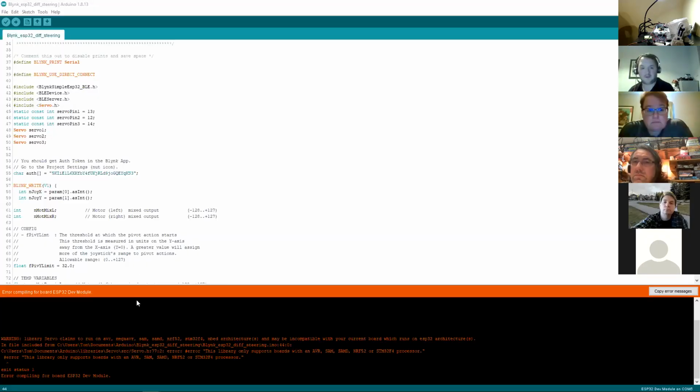Yeah, because how do I? Oh, this is. Have I shared that screen correctly? Yes. Yeah, that's what I'm getting. It's saying the library supports boards with AVR, SAM, SAMD, NRF, etc., but it's not happy with the ESP. Yeah, that's because I'm using, let me have a look to find it, an ESP32 servo library, which I need to find.